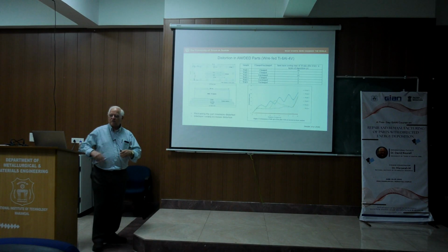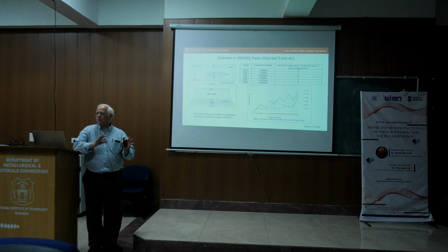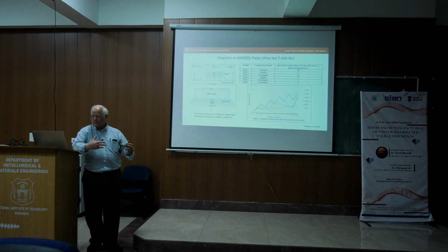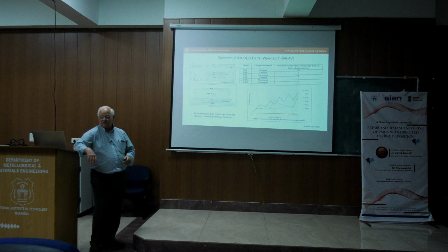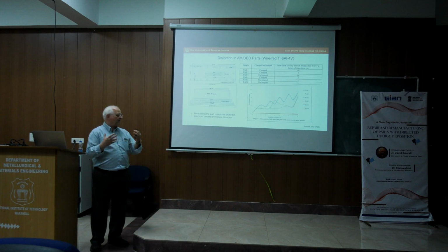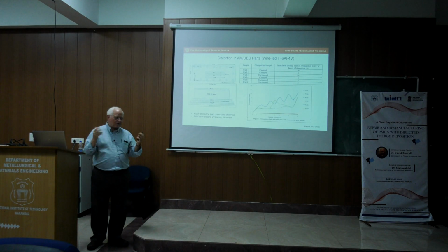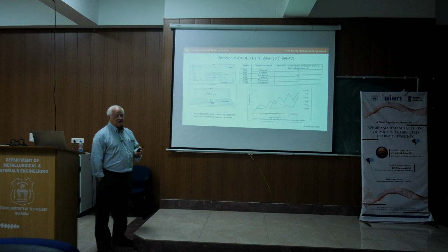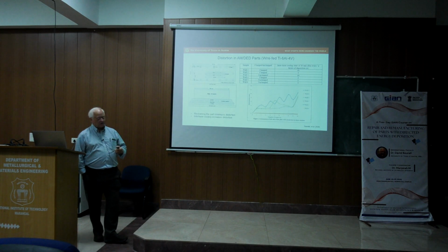They would lay some number of layers, then stop and let everything cool down in the DED, then do another number of layers, wait 30 minutes, and cool down. The number of layers they picked was either 2, 5, or 10 layers. So effectively, they run so many layers, stop, wait 30 minutes, and then go up. And it turns out that also has an impact on the distortion that occurs.